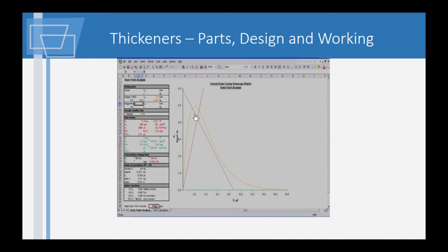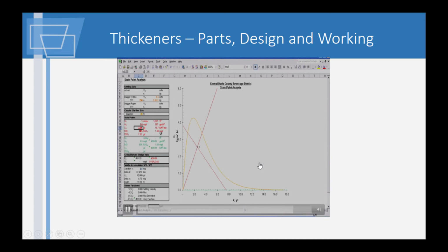So now we've seen some ways to avoid failure, but the state point diagram can also help optimize clarifier operation, not just prevent problems. Let's go back to our nice, properly functioning clarifier. The SVI is back to 250, the flow is 3 mgd with the RAS running at 50% or 1.5 mgd, and this time let's say that we've wasted.